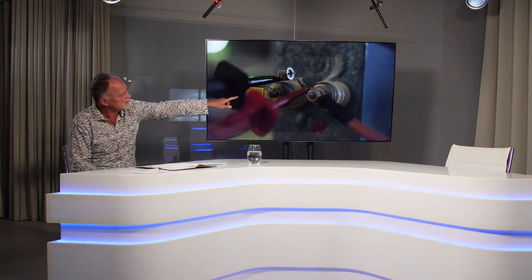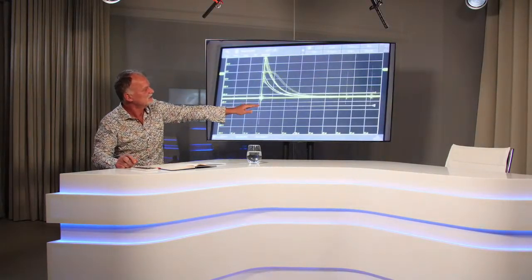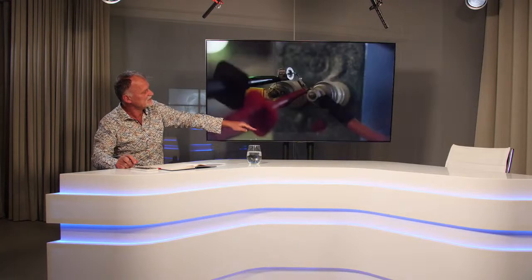And we have a discharger here, because if the capacitor goes over the voltage, it will break the oscilloscope, right? What you see here is the voltage increasing, and then the discharger discharges the capacitor, and that you see as a flash here, right? So that's a very standard way for the capacitor to charge. I believe that it's understandable.